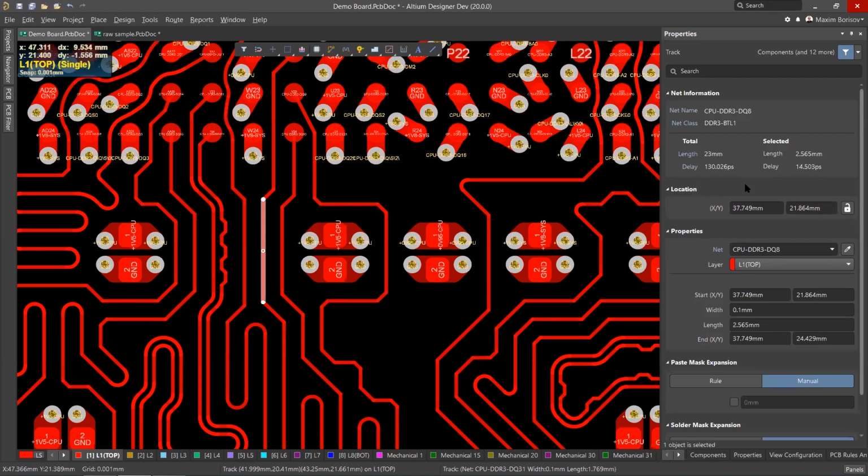It will recognize coupling within a differential pair, yes. And it will also take all physical parameters from your stack-up, including edge factor, covering with solder mask, amount and type of dielectrics, I mean the accurate physical structure of the whole transmission line.